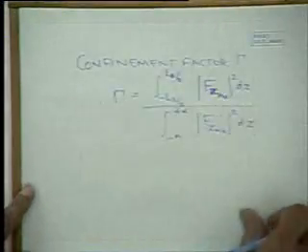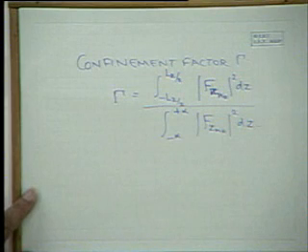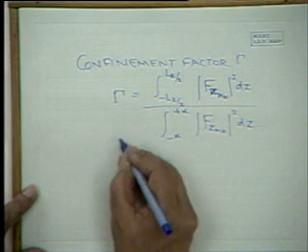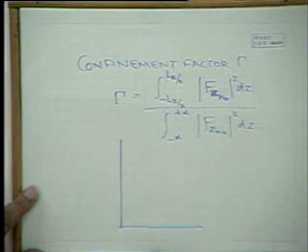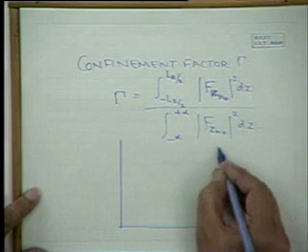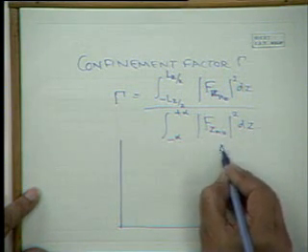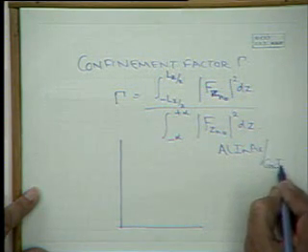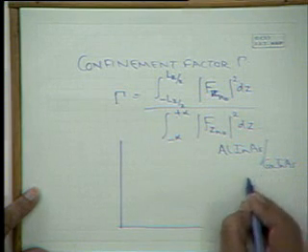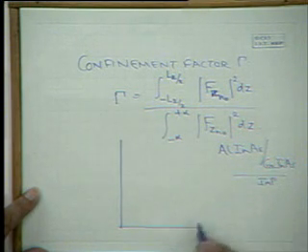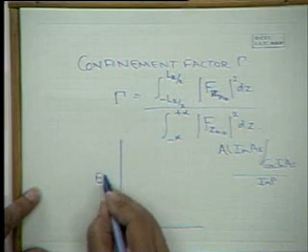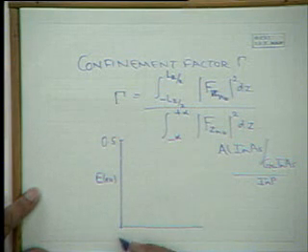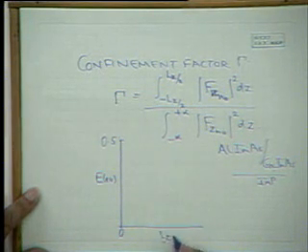Using these, one can actually calculate the bound state energies of a finite well. This is aluminium indium arsenide, gallium indium arsenide, lattice matched on indium phosphide substrate. This shows the bound energies going up to about, say, 0.5, and this is LZ in angstroms.